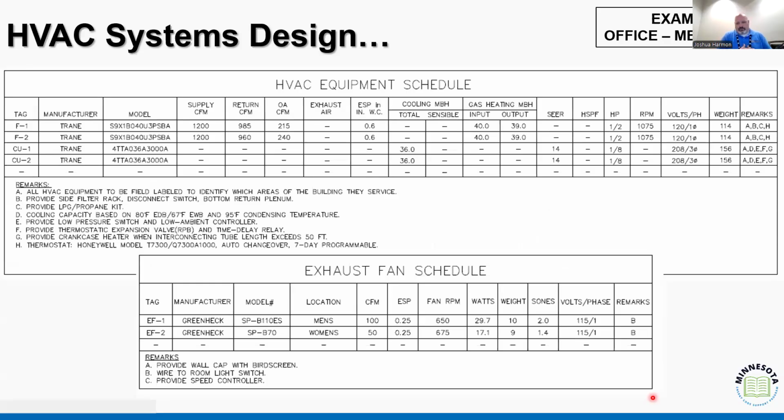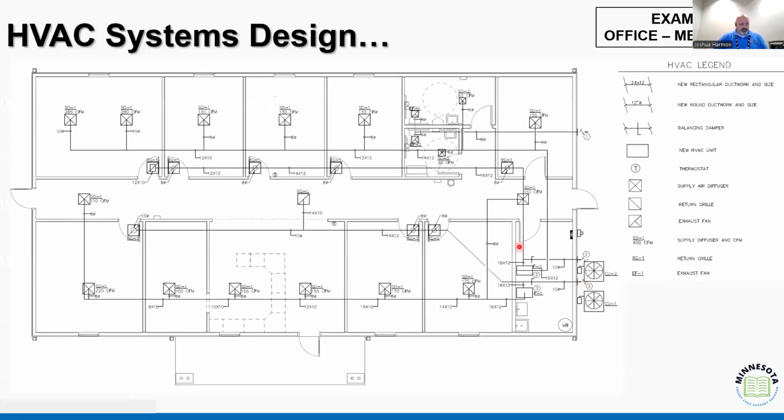One thing I miss, and maybe you saw it, but I didn't see it in those 3 slides, was any type of load calculation. I saw that you identified equipment. I see that you gave those equipment some controls, right? The 7-day programmable control, auto changeover, right? Appreciate that. You got exhaust, you calculated. You even got equipment sizes, right? You got some SEER sizes. We have efficiency ratings. But what you didn't do is tell me how much air your building needs.